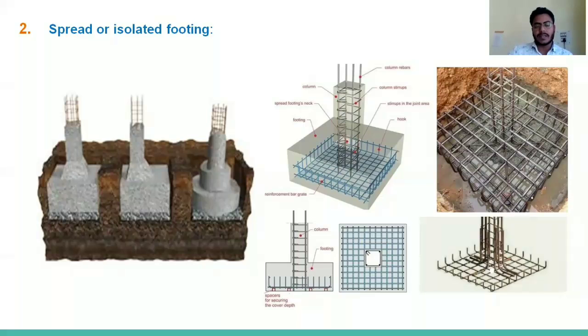So we have to reinforce at the bottom. Wherever in the concrete the tension is coming, we have to reinforce there only. We have to place a steel bar at that place, so that the steel bar will take the tension, because obviously concrete is weak in taking tension and stresses.